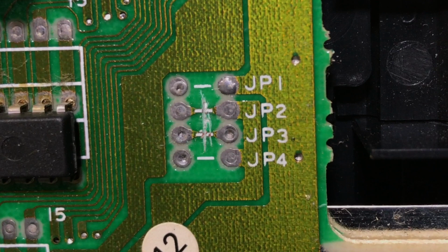Now you'll need to heat up your soldering iron and apply some solder to the right hand JP1 pad or the right hand JP3 pad, but I prefer JP1 as it makes things a little bit neater. You also need to apply some solder to the left hand JP2 pad and the left hand JP3 pad. You only need a little bit, so don't go overboard. You know you've done it okay if the solder is nice and shiny.